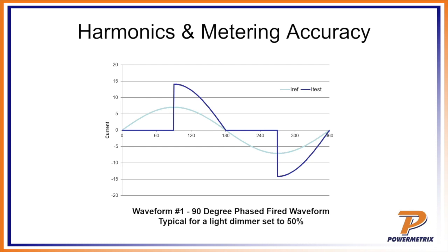Meters weren't good at measuring half a sine wave, simply because you had that really sharp edge, the sharp edge on the shark fin, that generated a ton of harmonics. As such, old meters had a really hard time metering that properly. So the ANSI committee said, okay, we're going to add this waveform. They define it up to the 20th harmonic.